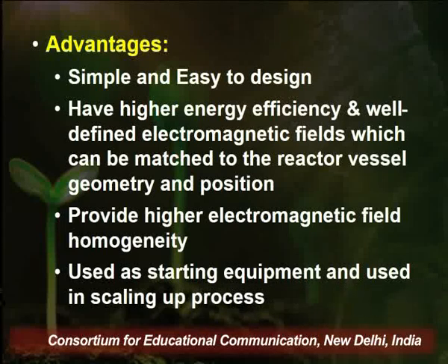And as the condenser is attached, the extraction that occurs in these types of cavities is normally at atmospheric pressure. But yes, there are monomode cavities also available which work at pressures above atmospheric pressure, which we will discuss further. These monomode cavities have higher energy efficiency and a well-defined electromagnetic field which can be matched to the reactive vessel geometry and position.